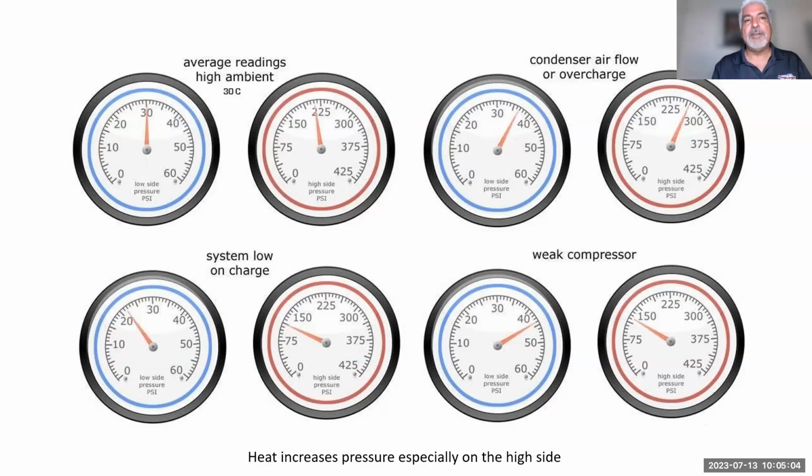Not to mention, if it is reaching close to 400 psi because of a restriction, let's say, does that prematurely destroy your compressor as well? Yes, that could shorten the life of a compressor. So I'm going after those guys that are replacing compressors. I hope you're not one of them, but if you're one of those guys that does a compressor every year on a truck, you need to ask yourself what took out the compressor. We talked in part 1 about the fan clutch issues on the Cummins applications, where they don't blow enough airflow at idle speeds. Therefore, that can destroy a compressor as well. So please note that you definitely have to have adequate airflow going across that condenser as well.